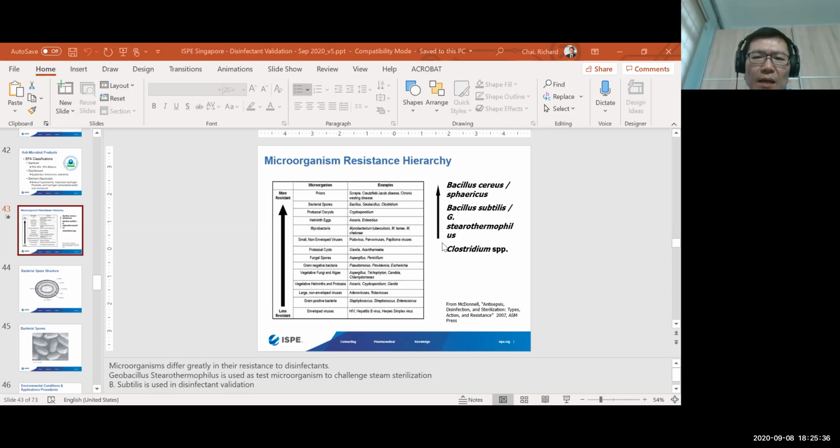Yeah, so absolutely it's necessary to have the baseline count. For new facilities, of course, after you have construction completed, the clean room completed, there are typically cleaning procedures in place to bring the clean room to meet the acceptance criteria in terms of viable and non-viable particulate counts, so that production can begin. During that period of reinstatement of the clean rooms, there's a series of cleaning.